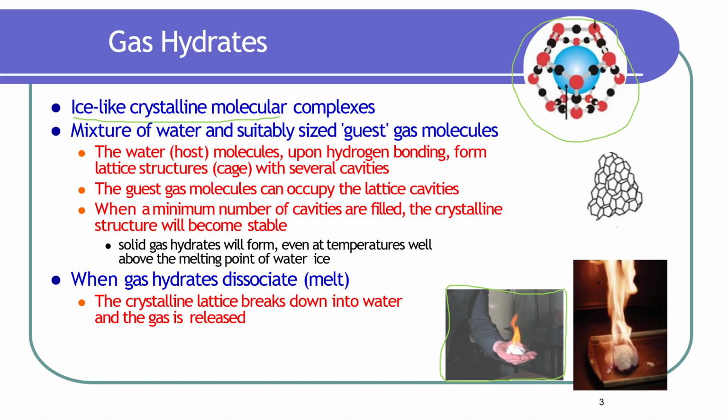So it looks like an ice, or an icy cube, or icy crystalline material, and this icy crystalline material is formed of water, and these water molecules can be represented here by the green dots or green circles that I'm going to draw. These water molecules are bonded to each other through a mechanism, or through specific chemical bonding called hydrogen bonding, and as a result this bonding will form something called the cage, which is the cage here. Okay, and the cage will be able to entrap the gas inside it. So these are the gas molecules that are really entrapped inside the crystalline structure of the hydrate.